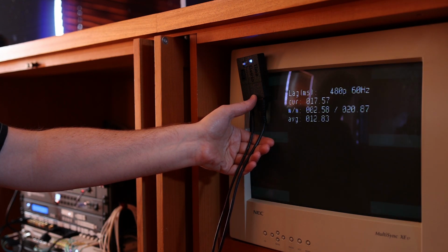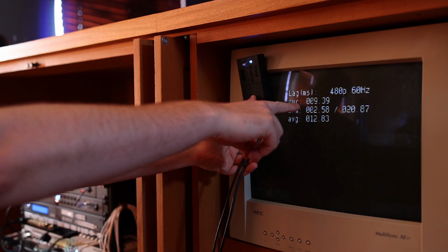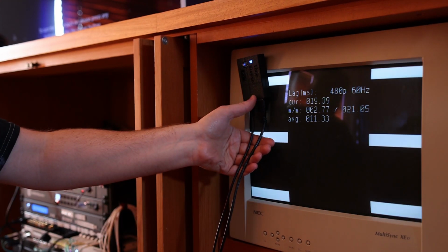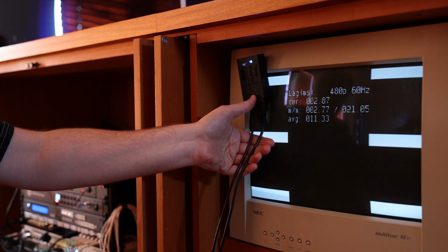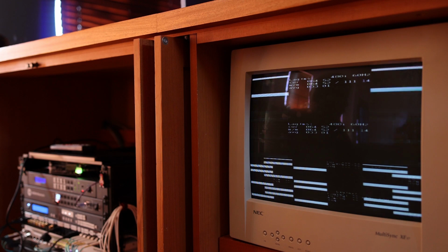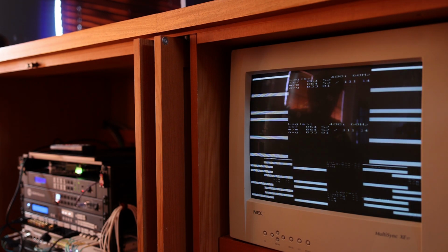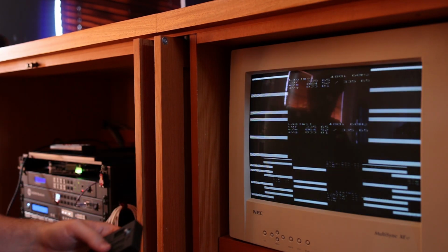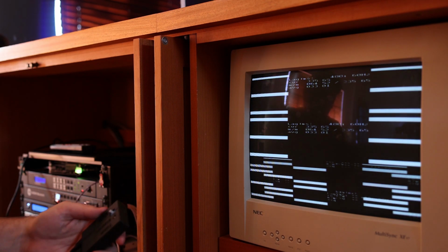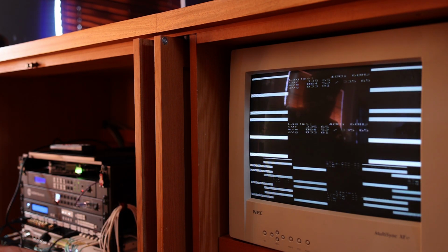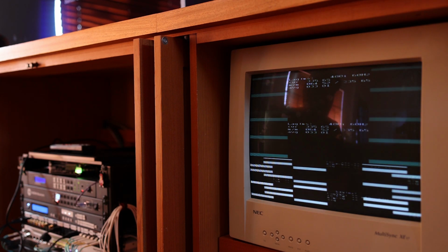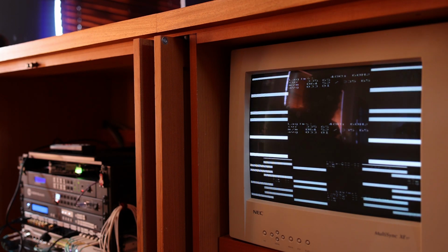And we can see this here as that value is constantly counting down, because that's basically the time difference between when one clock wants to send a signal and when the other clock wants to send the signal. It's very inconsistent over time. Different adapters work in very different ways. As you can see here, it can't even keep synchronization. A 480i signal, so interlaced, just does not want to work with this downscaler. If I set it to 240p, it just doesn't know what to do at all.